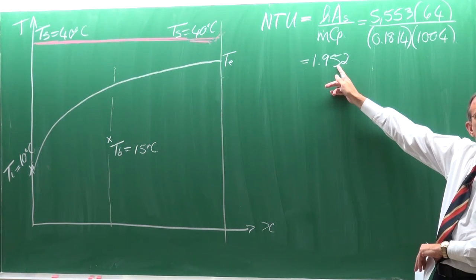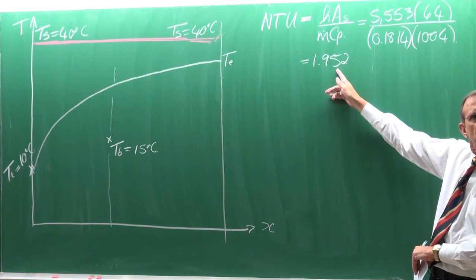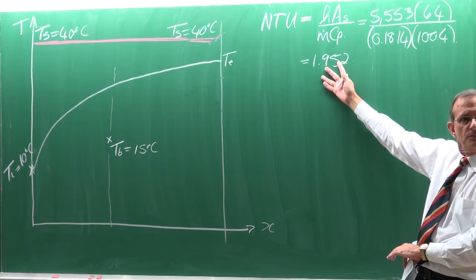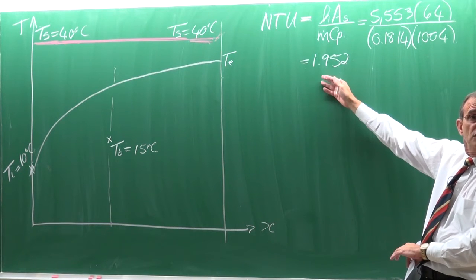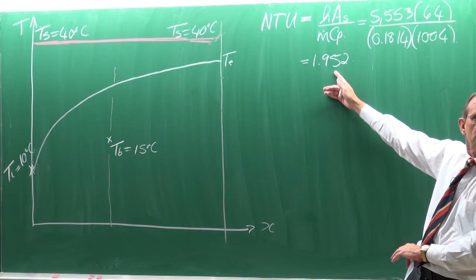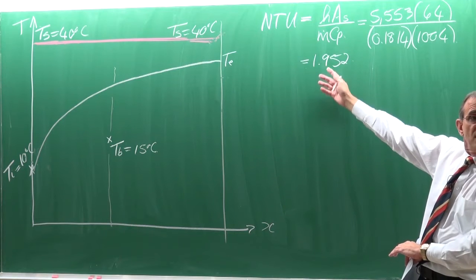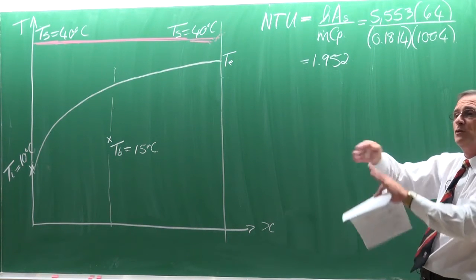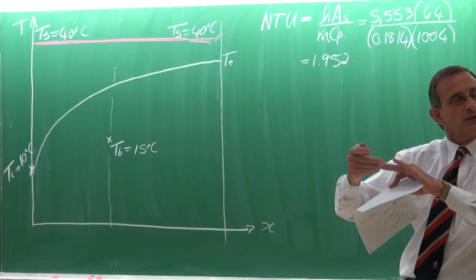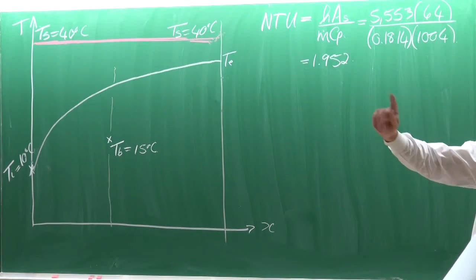This thing tells me a lot. It tells me that the inlet temperature is going to change significantly. If it's a very small value, you can know that there will almost be no heat transfer. If it's about 3, then I would know that the outlet temperature is going to be 40. Okay. So for design purposes, in many cases I designed for a value of 2. So even between 2 and 3, it's a big increase in length. Okay, but 2 is a good value, so this is close to 2. So it tells me that the inlet temperature is going to change significantly.